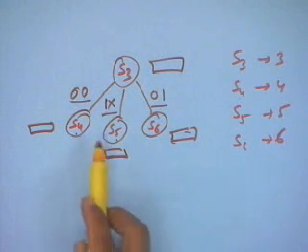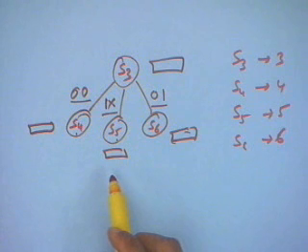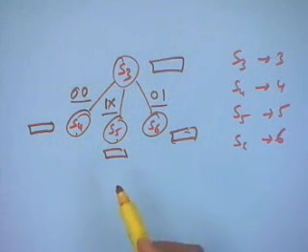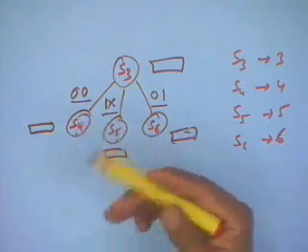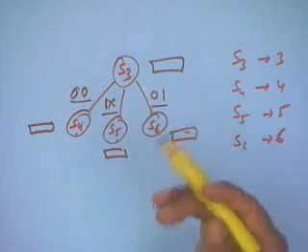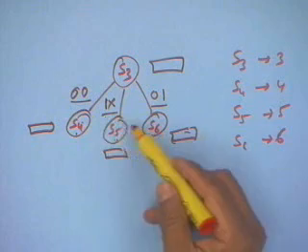I need to select between 3 of the micro instructions. Typically, as we will see with the sequencer, the next one can be generated automatically. The sequencer has a capability of jumping to the next one. But I would need 2 more addresses coming, and I have to choose between one of the 3.